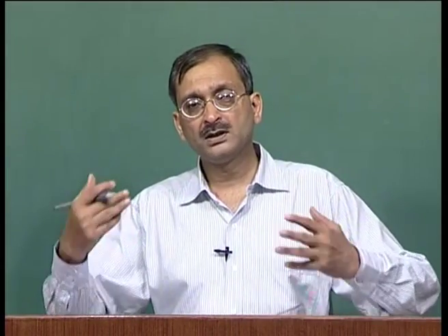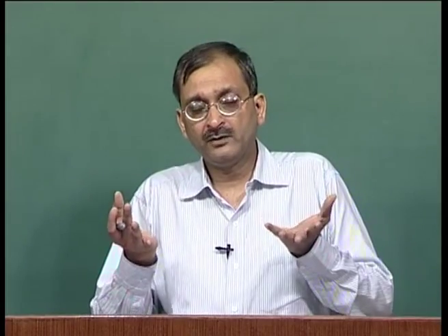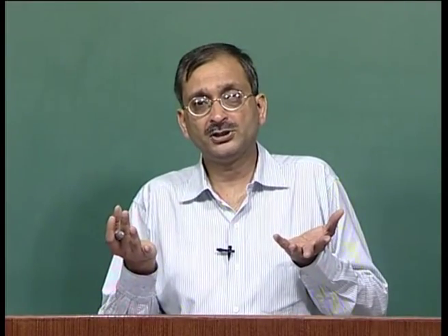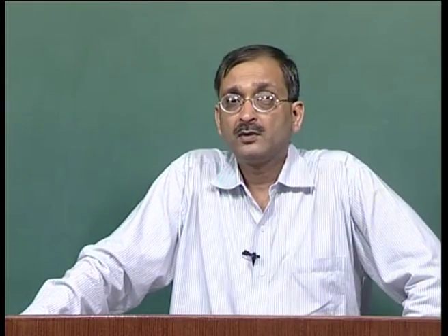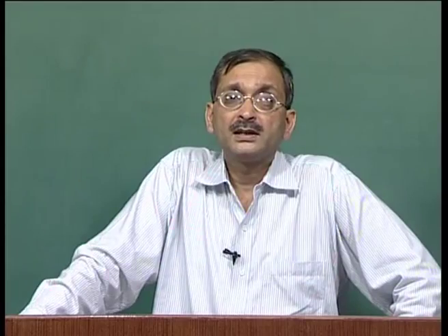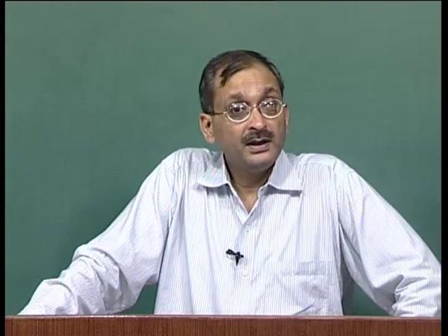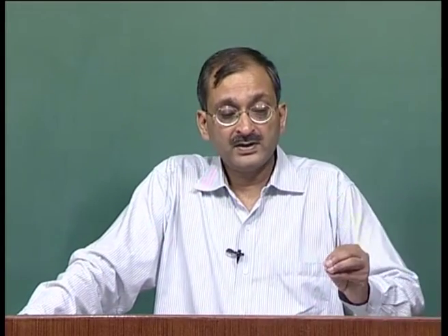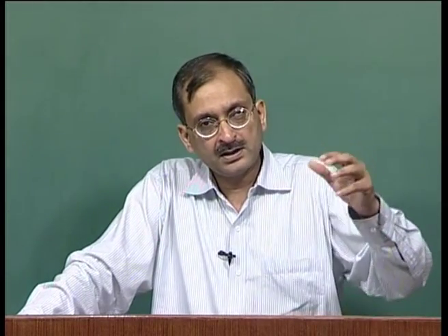Initially, the cone of depression formed due to the pumping. Once it is stopped, it is recovering. The aquifer system is recovering to its original position, so obviously, it is called the recuperation or recovery. Now, this recuperation process, will it be steady or unsteady? Obviously, it will be unsteady. As we said, initially the formation of the cone of depression is an unsteady process.